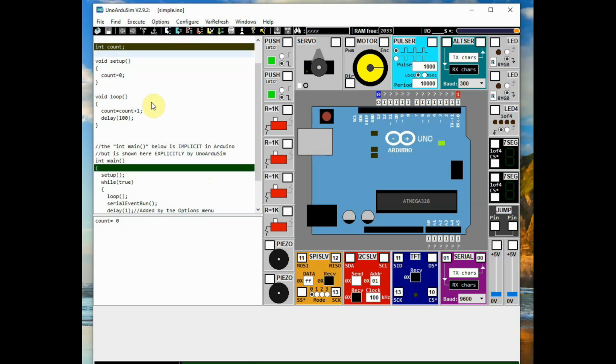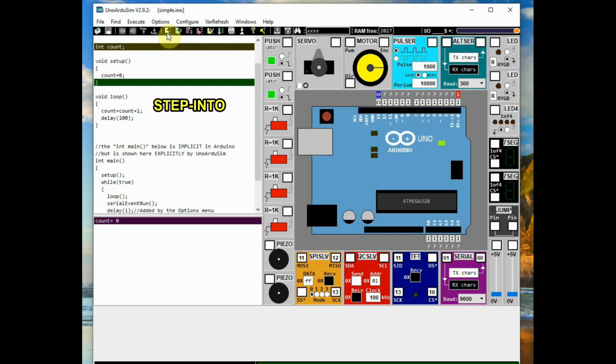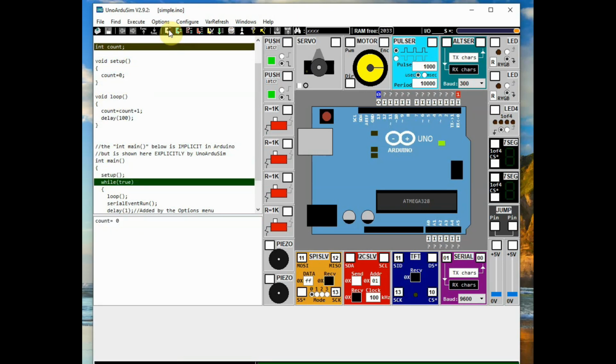There is also step over, that is you can press F5 also. It is used for step execution forward by one instruction or by one complete function call. There is also step out to leave from the current function, and then run to. You have to click to highlight a line and then use the run to, and then run till, which is used. You have to run the program until a write occurs to a variable highlight. So it is very powerful in this emulator.